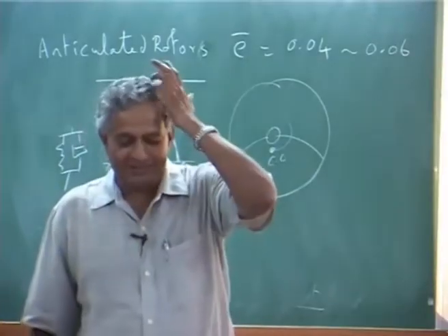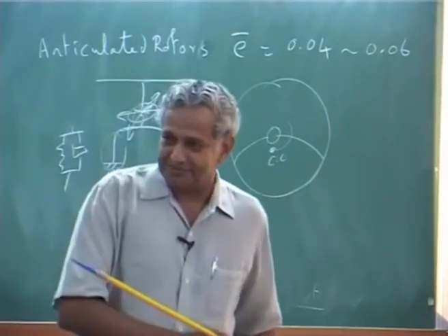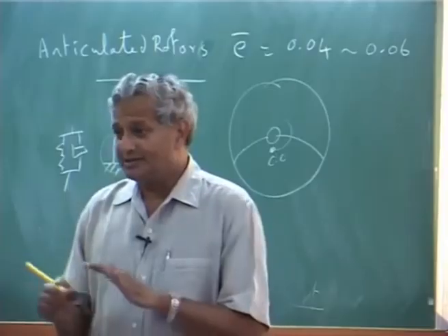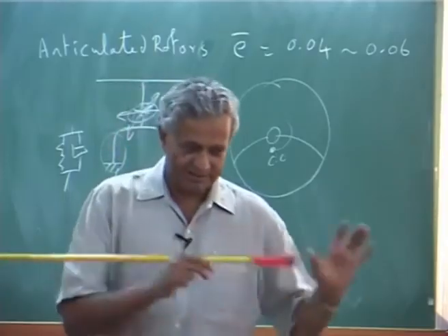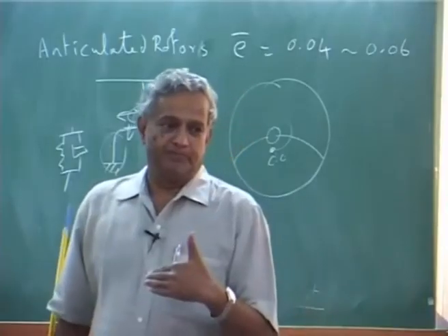So, usually there is a transformation that is done from rotating frame to non-rotating frame. That transformation is called the multi-blade coordinate transformation. Okay, there is a mathematical transformation, then you get it into fixed frame mode.